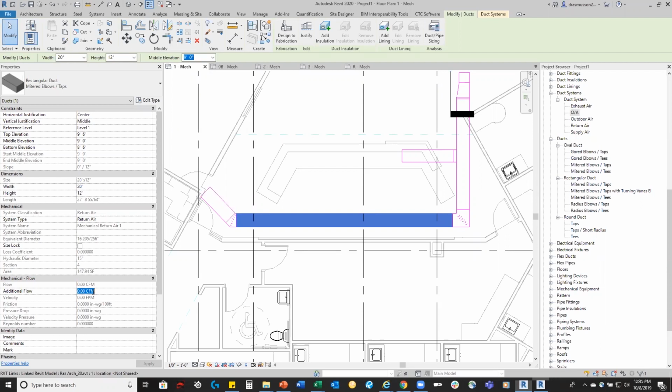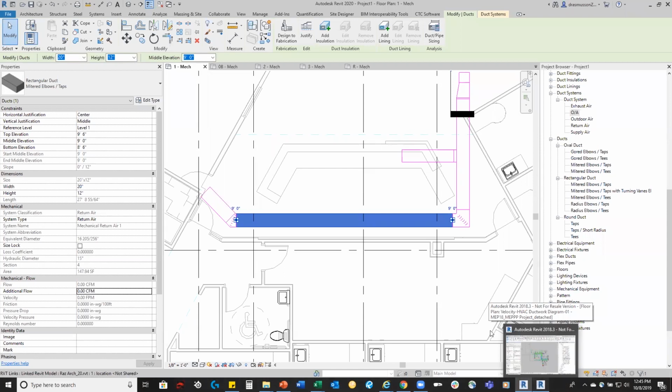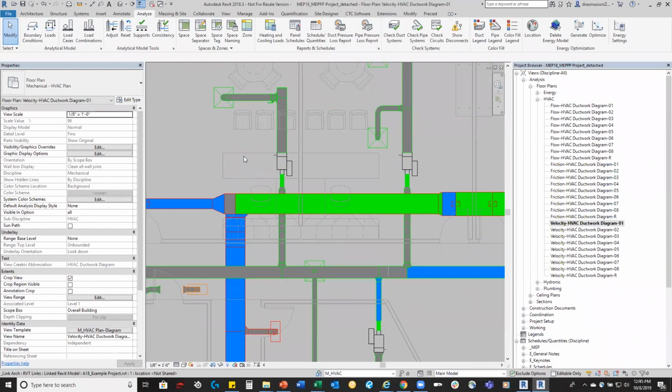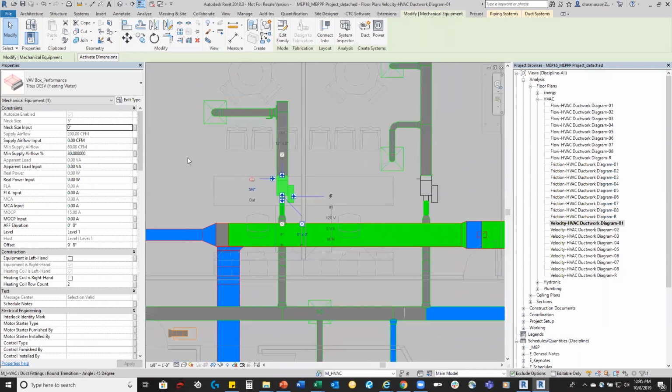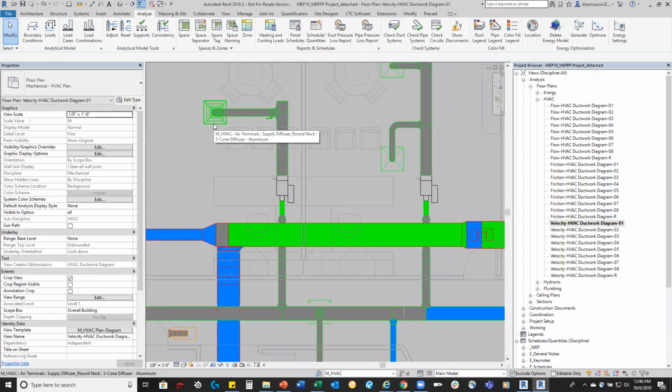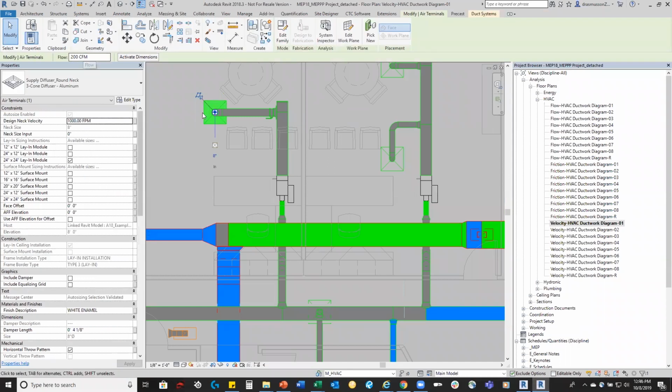We got a question about how we get our device airflow to add to the ductwork. Well, in order to first understand that, guys, we have to understand how Revit calculates flow. And this will be, unfortunately, the last question that I'm able to answer here before I have to get off. When ductwork is connected to devices, we have to understand what this device is reading. You see the minimum supply here on this VAV system, for example, is 60 CFM. The supply airflow is 200 CFM. But that airflow is not being driven by this VAV box. Revit sees things backwards. So Revit's looking here for that 200. That's where that's coming from. It then flows everything backwards down to your pieces of equipment.